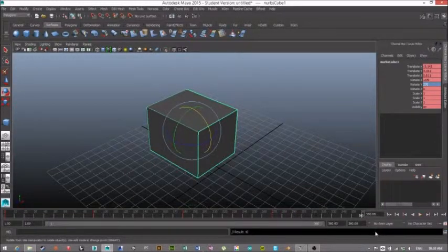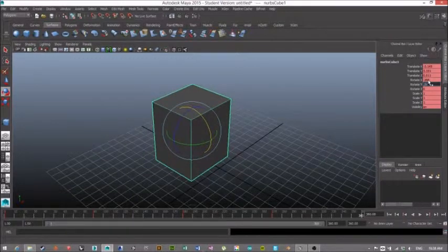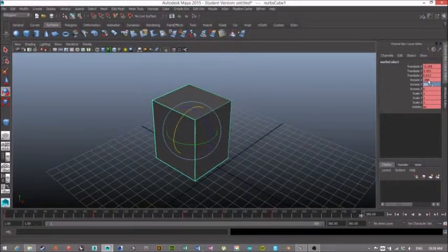And then if we want this thing to loop, so it just keeps playing over and over and over, all we'll do is bring the geometry back. But we don't want to bring it right back to 0, because what will not always happen, but can happen depending on the geometry you're working with, is it'll skip. It's trying to understand a consistent rotation. So we'll make this same kind of logic that we've been going with, 360 degrees, negative 360 and 360, and we'll just keyframe that again. So if we scrub through, we can see our thing is animated.